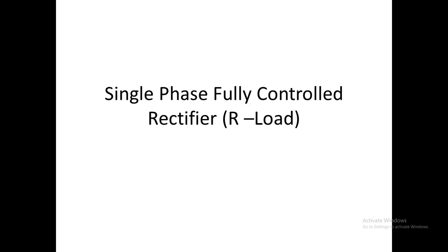And a fully controlled rectifier, in the sense it is a full wave rectifier, so we can get output in both the positive half cycle and negative half cycle. So a fully controlled rectifier means it is a full wave rectifier with a controlled device as SCR.